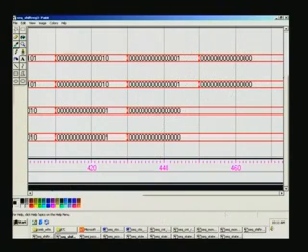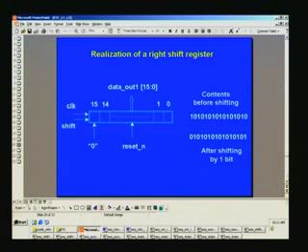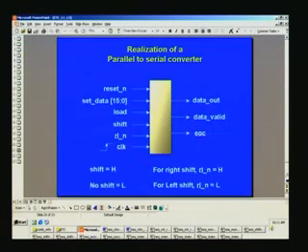So next we will move on to the parallel to serial converter we had seen. There's a reset. You can set the data and then load it, and then shift once you have loaded. So we have a 16-bit parallel information which will load into the shift register here, and then shift either left or right depending upon this control RLN, one being right shift, at the positive edge of the clock, so long as shift is valid.